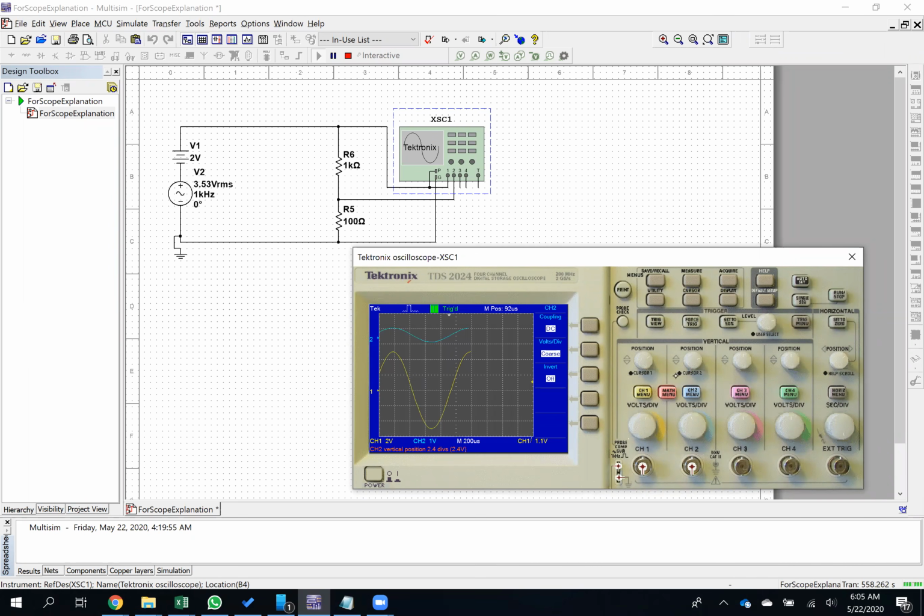So quite often what I would do is I would put channel 1 above, and I would put channel 2 below, right, when I'm taking measurements. And then in my mind, 1 is always above and 2 is below. Sometimes you might want to match up the grounds of channel 1 and channel 2, especially if you're taking a reading between shifted waveforms and you want to take accurate measurements, you might do that.